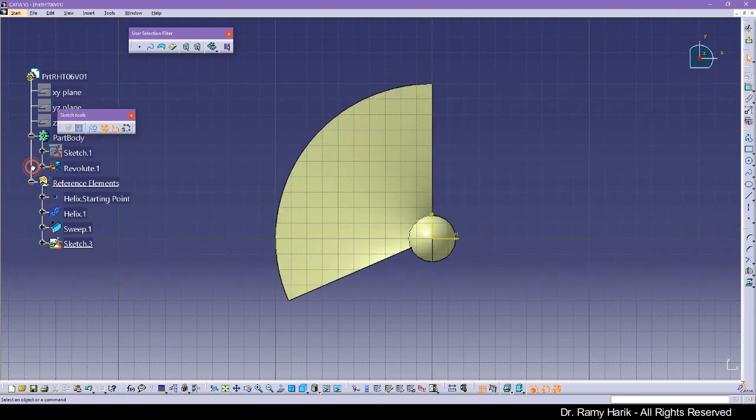And I'm gonna reactivate it. In order to make sure that the sketch projections can be used as is, we are going to select them one by one. So you can see in here what's happening. If I go ahead and select this one and I project it, so this is the project 3D elements.